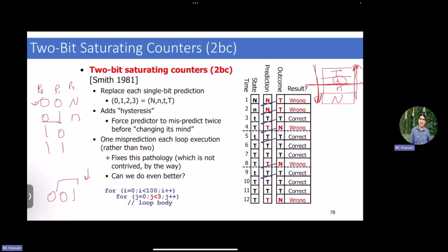But if we go back to our program here, what we said for this small thing is these, for example, are BEQs. Let's say they are BEQs. So I track the history of the BEQ. In the case of the directly past execution, it's the BHT, the single bit predictor. If I take the past two executions, similar to what we do here, this is a 2-bit saturating counter, right? But if I say, okay, no, these are two different BEQs, these two, for example,